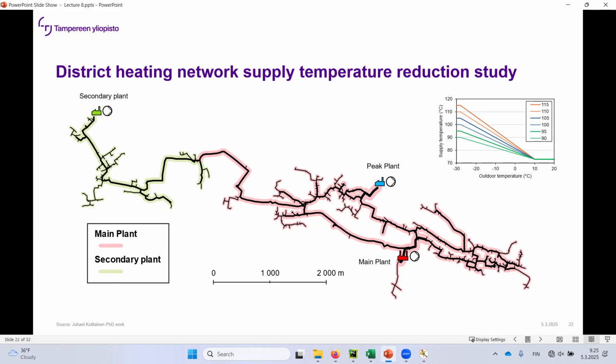You cannot just look at these networks in terms of energy balances or power balances, where I'm going to balance out with these plants: if the consumers have this much consumption, then we're going to have this much production, and that is based on the merit order. Yeah, basically that would be the ideal case, but since there are these flow limitations, they have to be taken into account. So more than just the merit order, the flow limits are going to affect this as well.